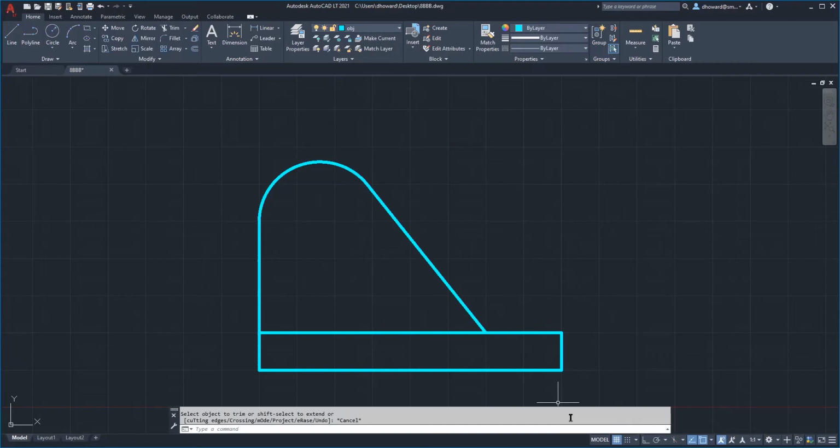It's called a fillet. So filleting automatically places a round between two lines. So this is an advanced move for you. It's right up here. It's in the modify menu right there. There it is. Click fillet. The radius right now is small. It doesn't have a radius. So before you can use it, you have to give the radius a value. So before you use it, you have to type, I know it's strange, but you have to type R and then enter. And you have to give it a value.